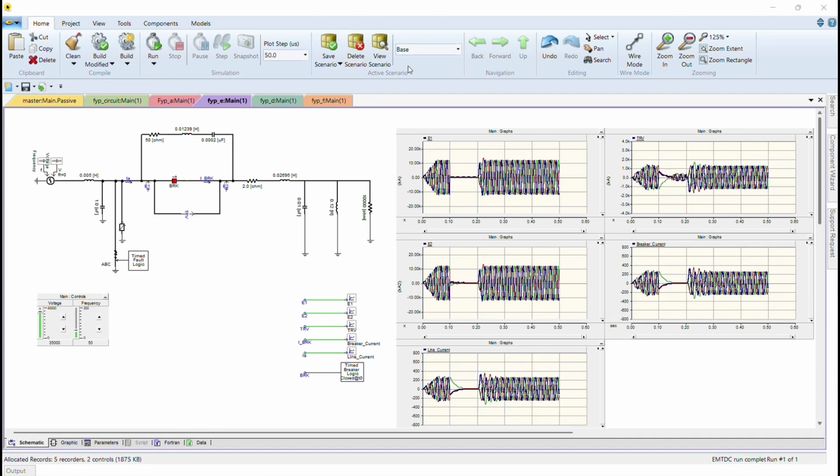Okay, as you can see, for E1, the voltage fluctuation is much smaller compared to the previous graph without the surge resistor. For E2, like E1, the voltage has also stabilized with less extreme oscillation. For TRV, the TRV shows much smaller oscillation. With the surge resistor in place, the TRV is more controlled.